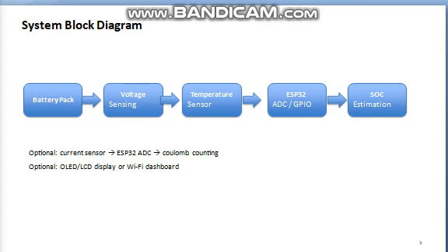So we will write the coding for that SOC estimation, and you can also add some more things in the block diagram, such as an LCD display or Wi-Fi dashboard, or if you want, current sensors also, to see how much current is flowing into the battery. That also if you want you can add. So here we have shown only voltage monitoring alone.